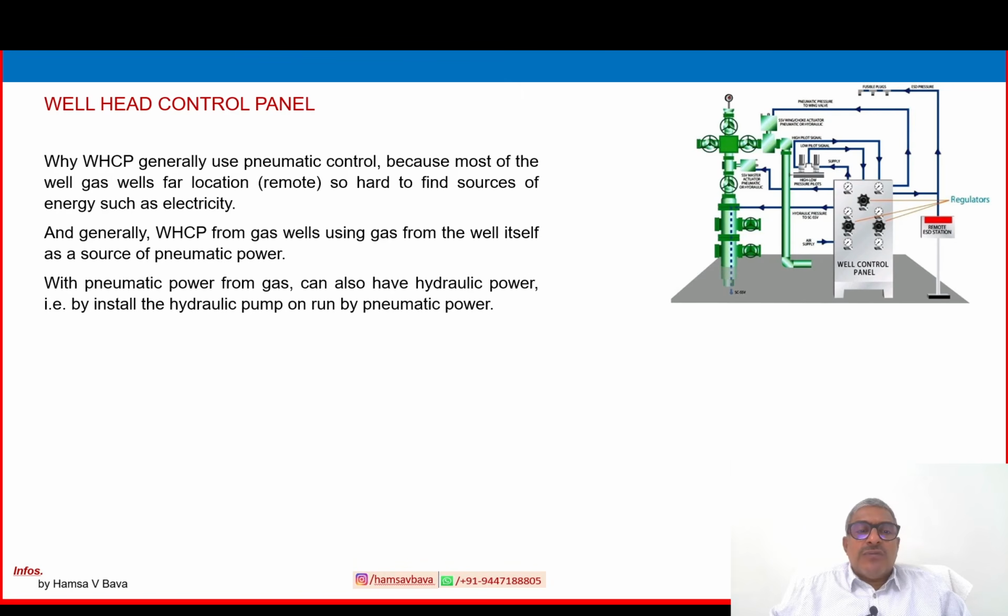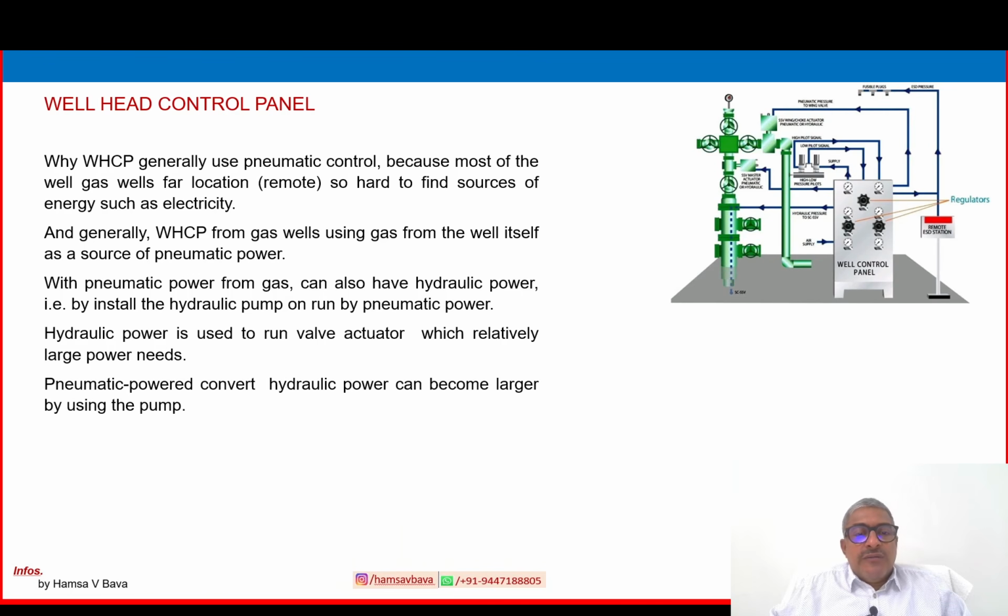With the pneumatic power of the gas we can also have hydraulic power, by installing a hydraulic pump run by pneumatic power. That is also possible. Hydraulic power is used to run the valve actuator, which has relatively large power needs. Pneumatic power converted to hydraulic power can become larger by using the pump.